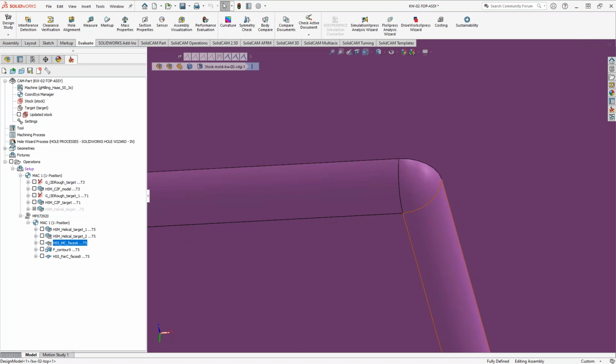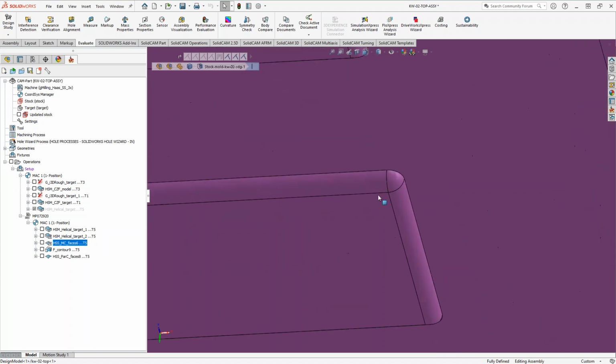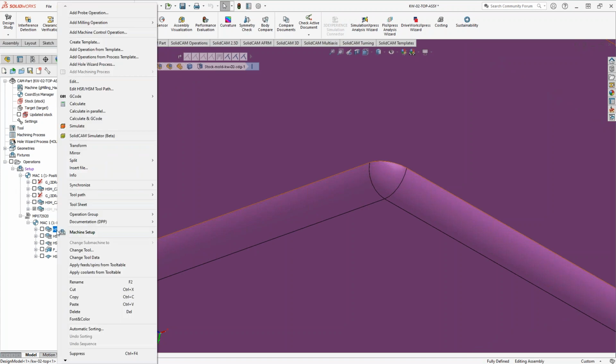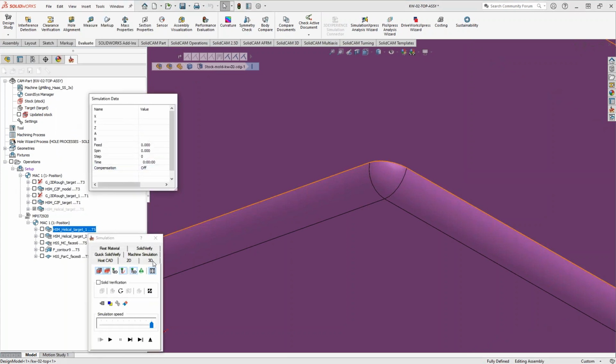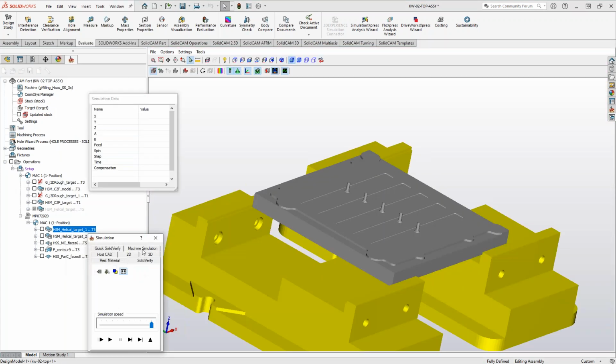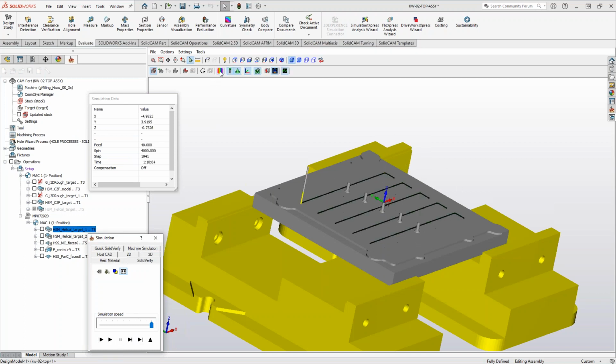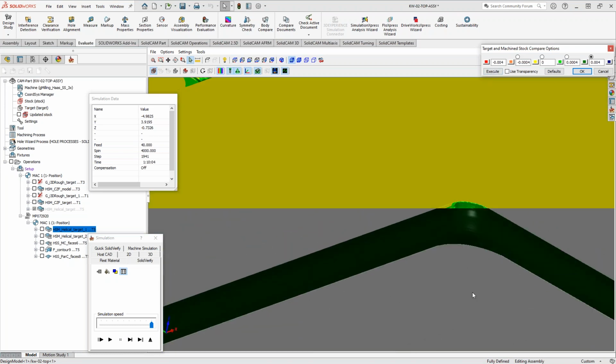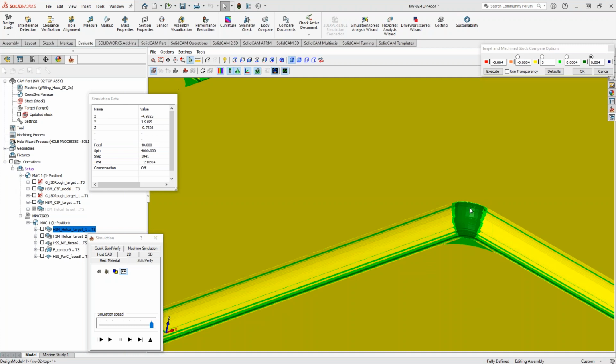3D corner offset, yeah. But this looks more like it's even more applicable for profile if the tool was on size, or if we could kind of, I mean, with that HSM, if we take a look at the Solid Verify, it's essentially what's going to happen anyway, regardless of if we follow that design or not. We're going to be leaving material behind in that corner because of the size of the tool. So the corner is smaller than the tool, so we're actually still leaving material behind there.